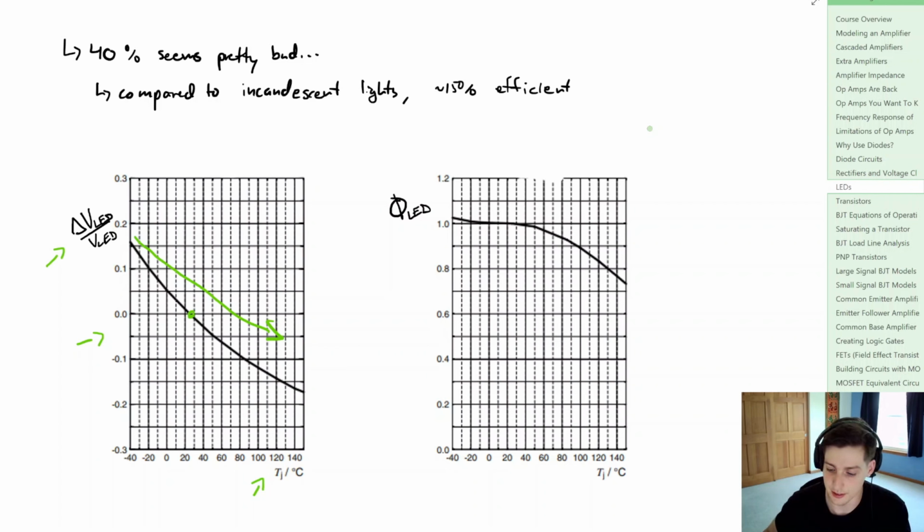you will also be decreasing the lumens, or the light per se, that you're outputting of the LED. So on the right here, we're looking at the flux denoted by this. So that's going to be the lumens value. And then horizontally, we're looking at the junction temperature. So if we mark our point at about 25C, you can see that it's quite normalized here. And if we heat up that junction, you can see that we have a pretty quick decrease in the lumens.